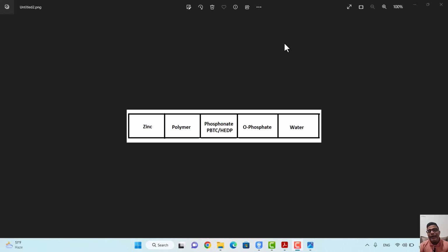And we categorize them against this level of chlorine in water, and we said that PBTC is the most powerful phosphonate in terms of resistance to a high level of chlorine. When we have a cooling water in which there is an abundant, excess amount of chlorine, we use PBTC as the phosphonate.